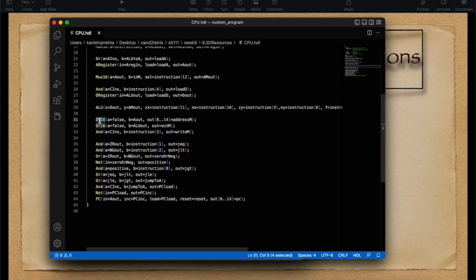Next is our OR16 gate. It sets the output pin to A out, and the opcode will be 0 as the A instruction opcode is 0. As we know, if it is an A instruction, then the opcode is 0. This is our OR gate, and it also sets the output to the ALU out. Next is our AND gate. It controls what's in the M register, and instruction 3 is selected. It will update the value of the memory register with what needs to be written in it.